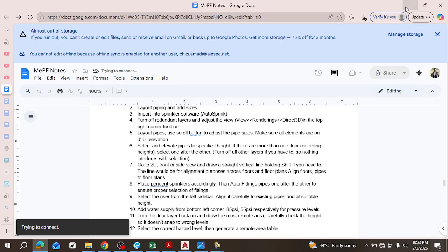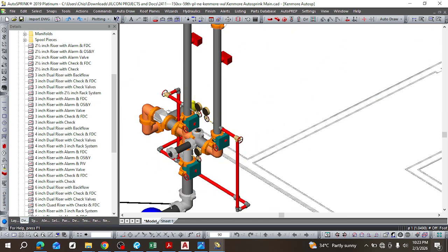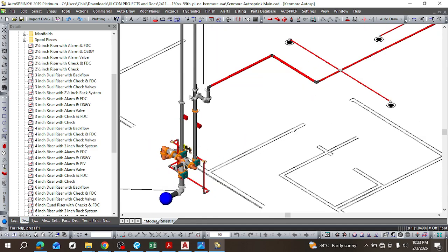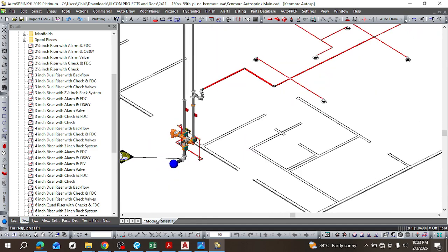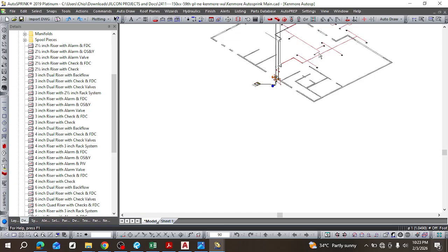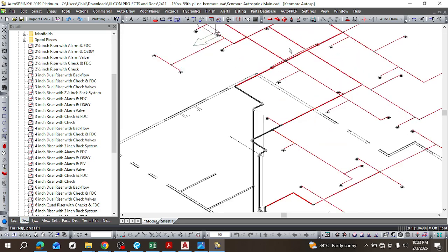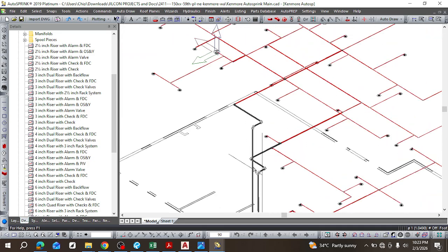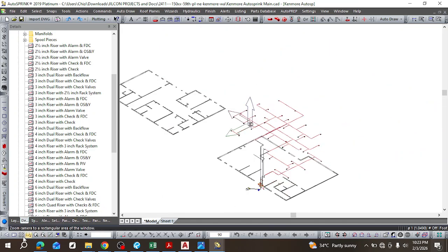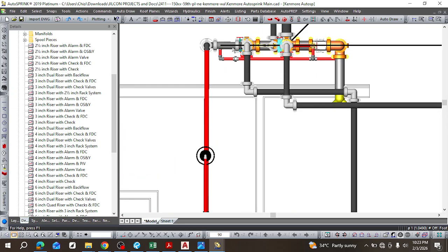Now the whole point of aligning all the floors was so that when it's time to select our riser, we'll just simply connect the outlet. There's an inlet here to our riser, and then this is the riser, and then connect each of the outlets, each of the inlets to the different floors. This is the basement floor, and this next height is the first floor. Then you see another one which is at the last floor, right? So the whole point is all of them meeting at that same spot. So when you look at it from the plan view, you see that they're all clustered in this area, right? That makes it easier for you to align all of them accordingly, right?